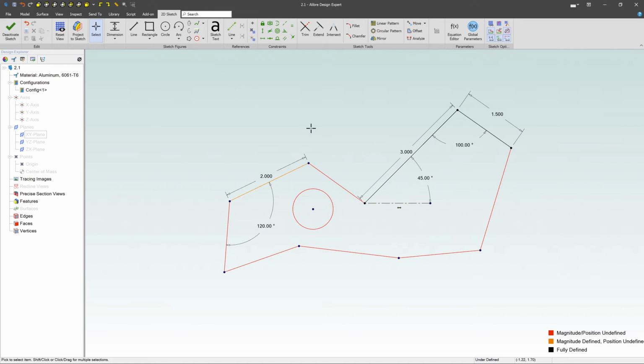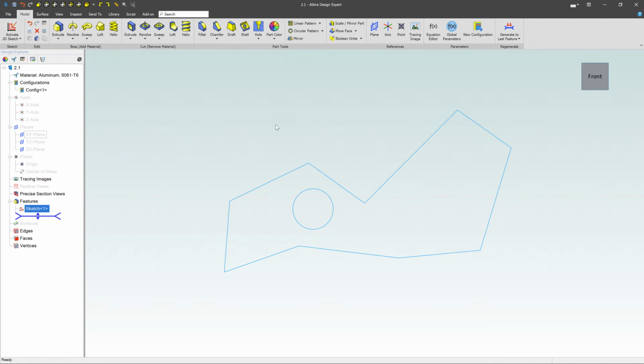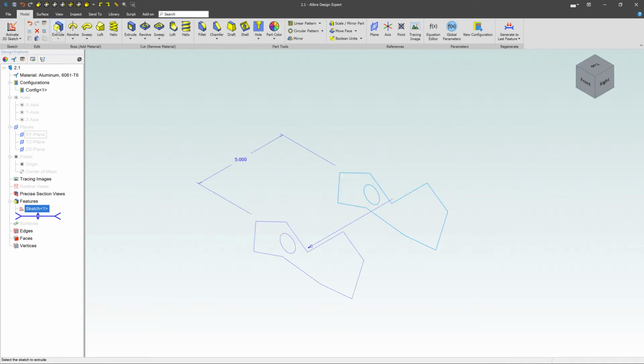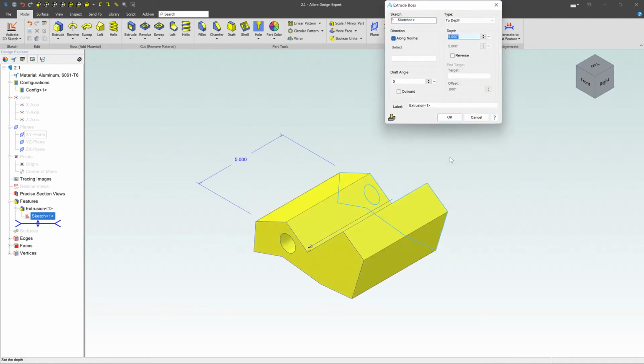So right now, let's just go ahead and turn this into a solid so you can see what I mean by an enclosed boundary. So deactivate sketch is one option. So just go ahead and deactivate it. And then I can say extrude. And notice what happens. It takes that shape and it extrudes it out. Notice our little island here, right? It's got a hole in it, right?